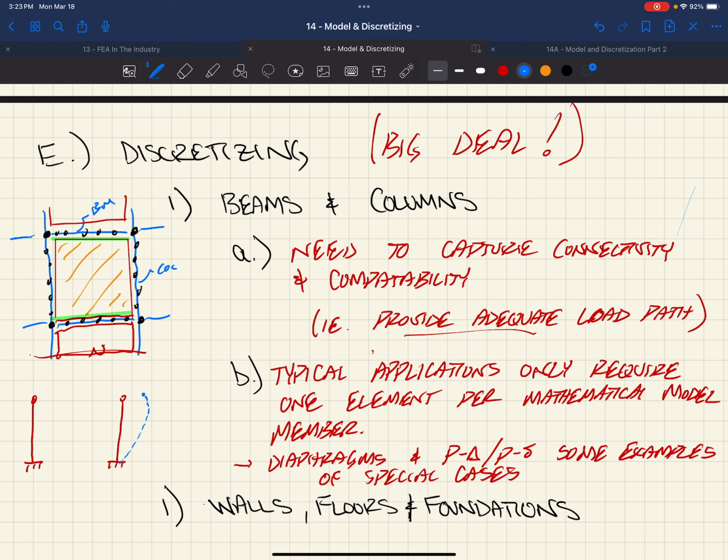If we had a force on this cantilever, a vertical and horizontal force on this cantilever, the horizontal force is going to create a displacement, and then that vertical force now all of a sudden is going to be based at some small amount of delta, right? Big delta.